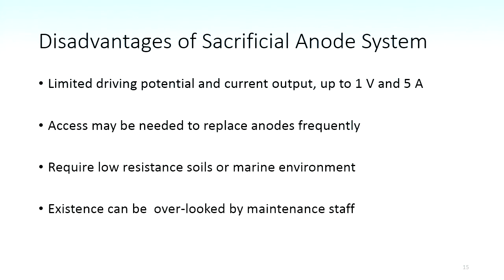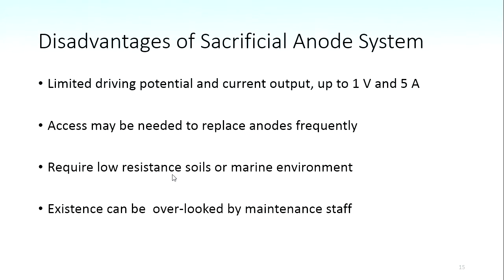Yes, sir. For example, for about a 10 kilometer long pipeline, what amount of cathodic protection do you usually use? Okay, so what you've got to do is try to achieve a control potential, and there are standards for that, ISO and NORSOK standards, which we're going to talk about later. But you want to get down past about minus 850 millivolts copper sulfate. We're going to talk about potentials and design of the system later. We're just getting principles at this stage.